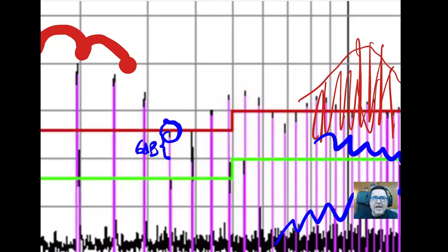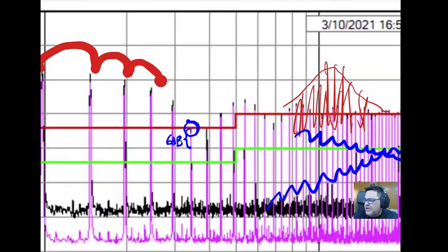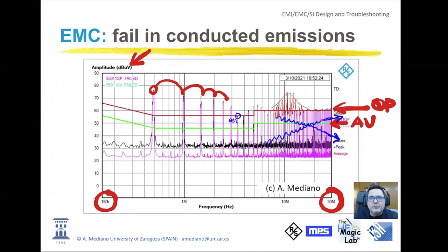And usually we will try to do this by redesigning the circuit with the components, the layout, or applying a spread spectrum like Florian was explaining in the first talk, or we will try to solve this problem traditionally by filtering. Filters are expensive, are big, and the most strategic work is to try to minimize the size and the order of this filter.